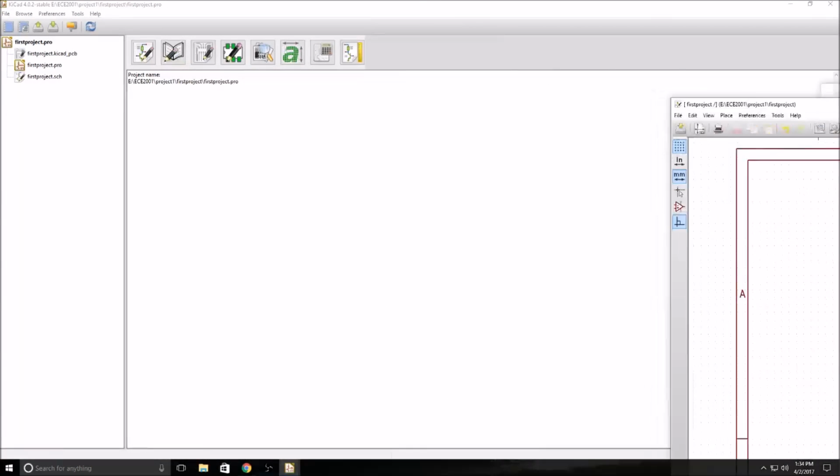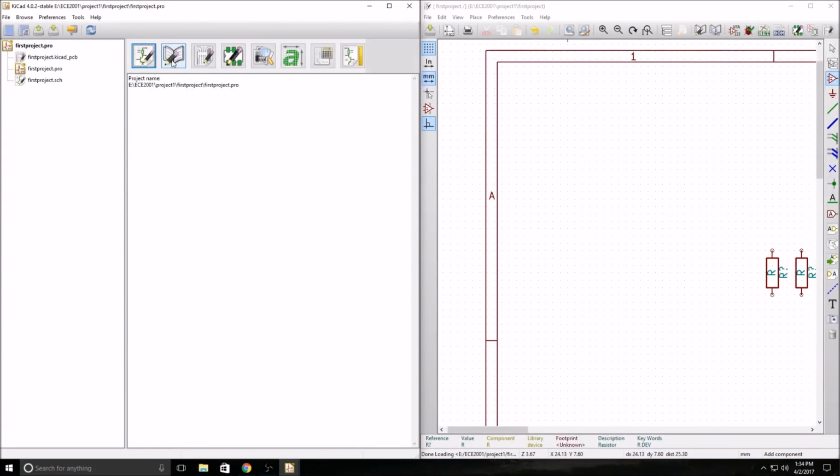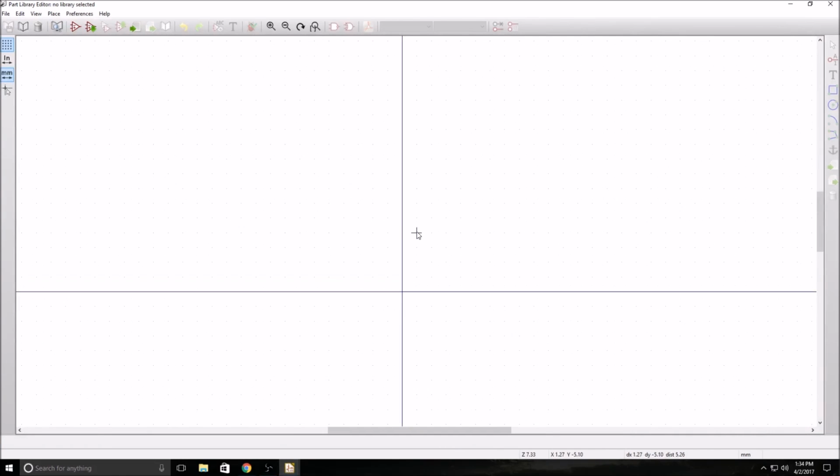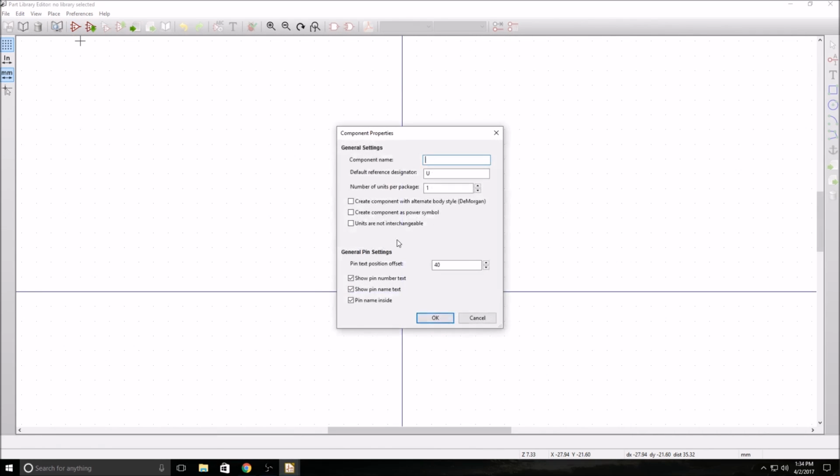We'll make our own component for that by going over to the schematic library editor. Okay, that shows up this page here. We need to create a new component, so we click on create new component. I'm going to name it TL074ACN. The designator is a reference.